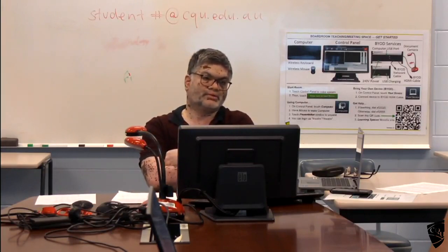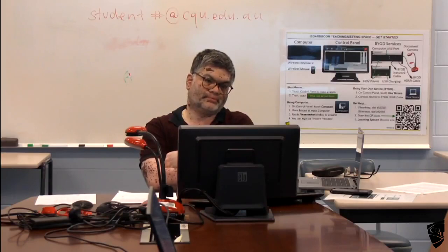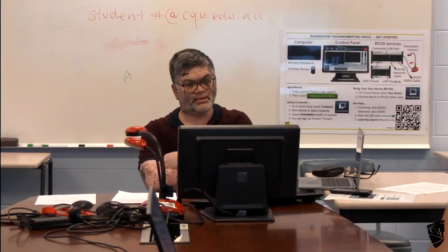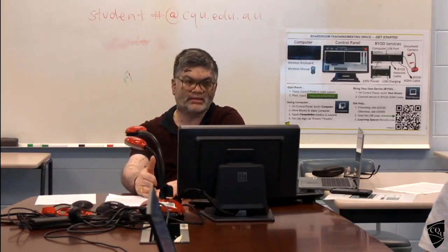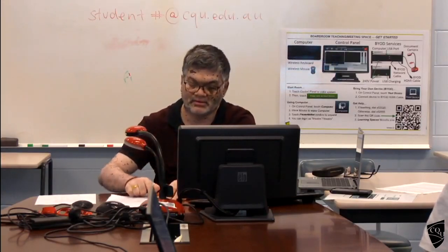It is not. We have two different strips here. We have the column strip and the middle strip. So the total moment is 100 here, or if it is at mid span, somewhere here, you should be able to find out. So the bending moment will give some values for the whole design strip, but it is not uniformly distributed between the column strip and the middle strip. It's a little bit different because the column strip will take more moment.